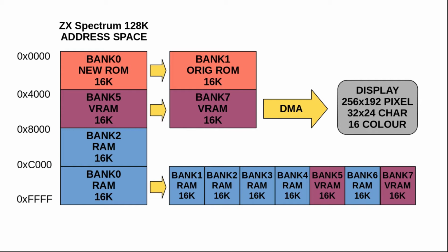None of the ROM can get switched into here, but all of the RAM can get switched, including the video RAM and the bank 2 RAM, which is also already in the physical areas above this area. So that's how they actually do the bank switching.